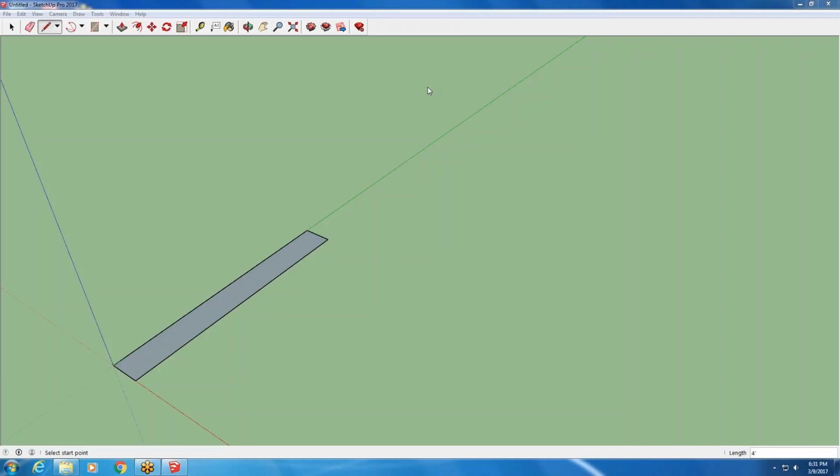I know you're not going to have a lot until you try it yourself. Do double lines matter in SketchUp? Definitely not like they would in AutoCAD. You're never going to tell in modeling if they're directly over each other. So notice there is no double line. I need you to understand that that wasn't a double line.